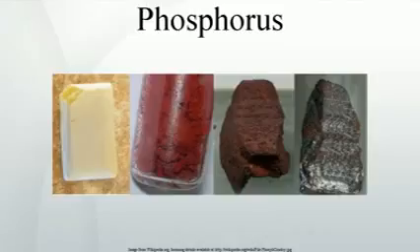The method started by roasting bones, then employed the use of clay retorts encased in a very hot brick furnace to distill out the highly toxic elemental phosphorus product. Alternately, precipitated phosphates could be made from ground-up bones that had been degreased and treated with strong acids. White phosphorus could then be made by heating the precipitated phosphates, mixed with ground coal or charcoal in an iron pot, and distilling off phosphorus vapor in a retort. Carbon monoxide and other flammable gases produced during the reduction process were burnt off in a flare stack.